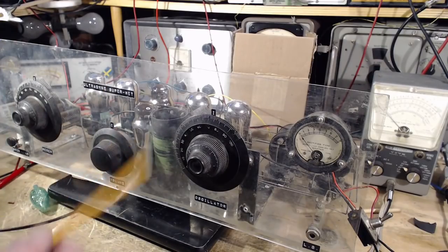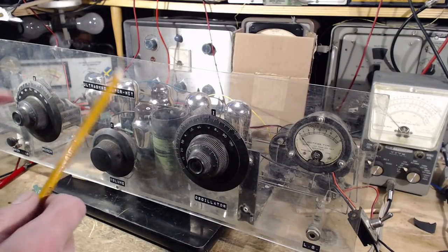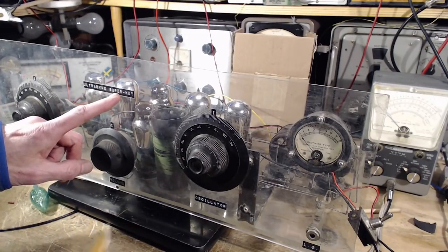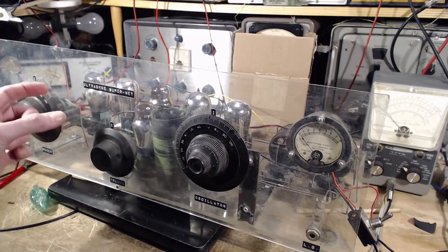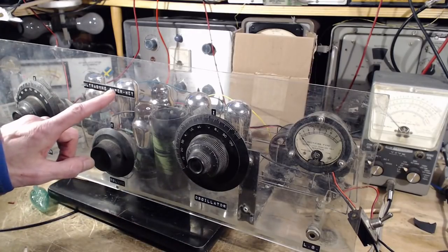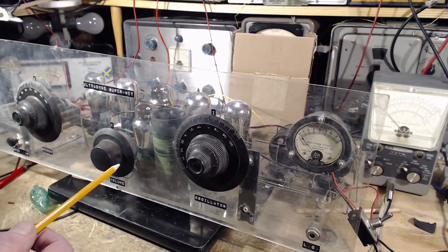And this is one of the earliest radios to attempt to heterodyne signals. So it's called a super heterodyne, by the way. The word super means beyond your hearing, because there were earlier heterodyne radios that heterodyned right in the audio frequency, and what that's all about I don't know. So that's where the word super comes from, because it's beyond your hearing. In this radio it's 100 kilohertz.